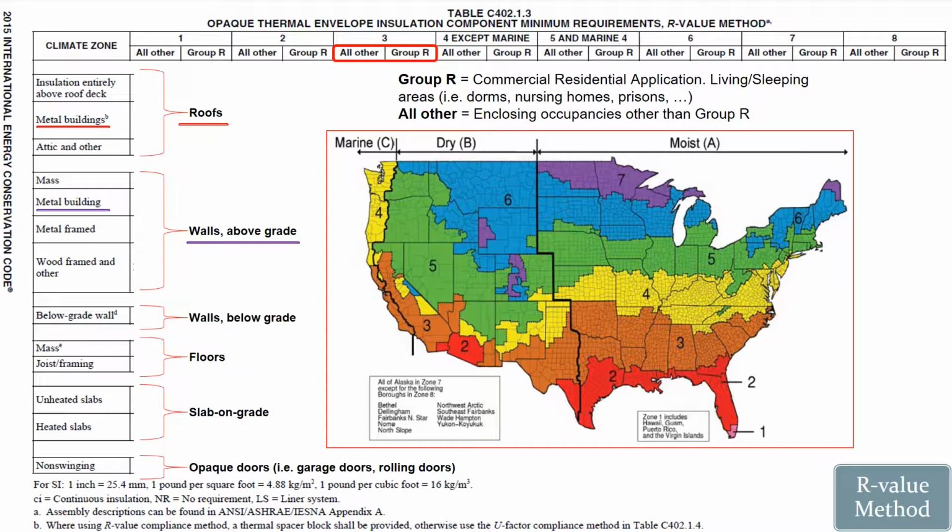Now, as mentioned in part 1 of the webinar series, even though you have a metal building which is defined as having purlins, C or Z shaped, spaced 5 feet on center on average, or walls with C or Z shaped girts spaced roughly 5 feet on center, you may have a different type of roof, whereas the insulation is not installed in and around the purlins for the roof.